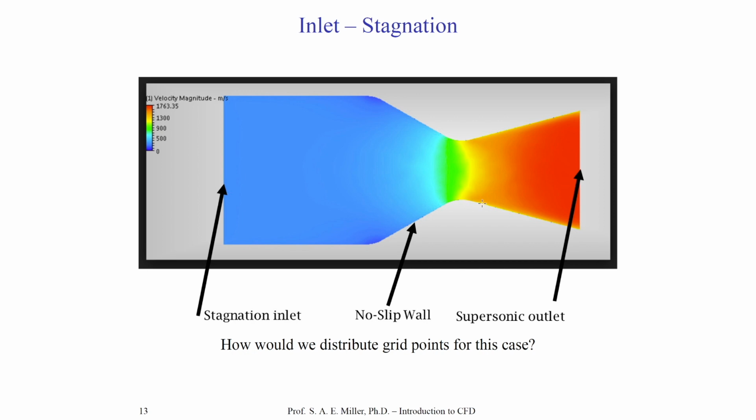You can see the strange variation of the velocity magnitude near the wall here. It's a little bit discolored, and that's because there's a turbulent boundary layer there. You can see how tiny the turbulent boundary layer is relative to the rest of the fluid, which appears to be almost of uniform magnitude. But remember, it's not really uniform magnitude. It's just the colors are not fine enough to see.